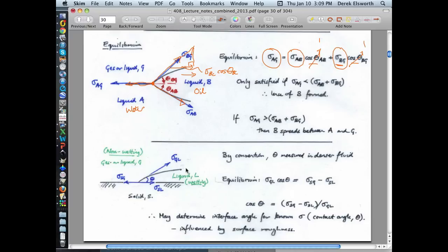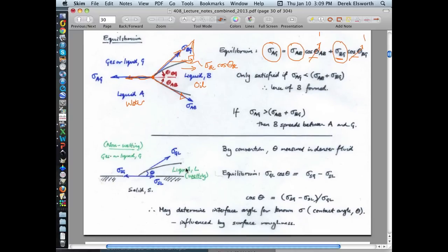And it's important to know that because you can imagine that if you're trying to push fluids through a porous medium, and of course quartz is basically glass beads, it basically behaves as a glass surface that you're trying to push stuff through. And if it's not going to spread very easily across this medium, then you're going to have a lot of pressure to apply to push it across.